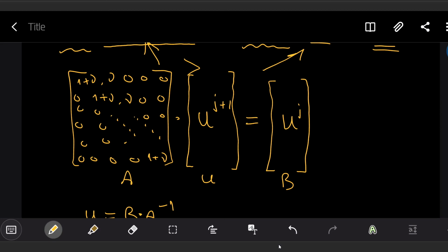The equations of the flow, the Navier-Stokes equations, are not linear, so it will not be such a straight relation. Actually, we do not have an exact solution for the Navier-Stokes equations. So in this case, we obtain the optimal Courant number from experience. It can be bigger than 1, it can be smaller than 1, it can be much bigger than 1, for example 10, 20, 50 for some simulations. For other simulations it can be really small, like 0.1 or even 0.01.